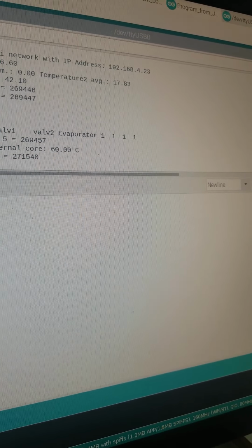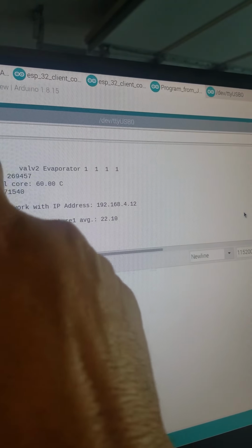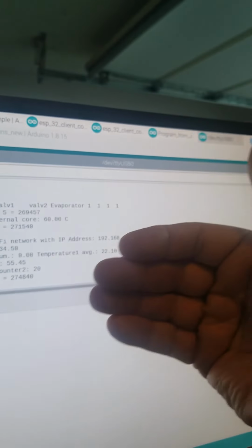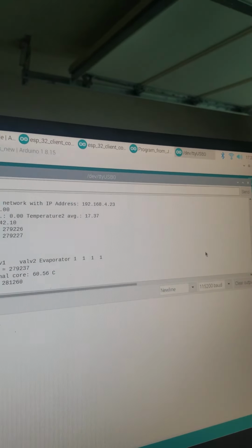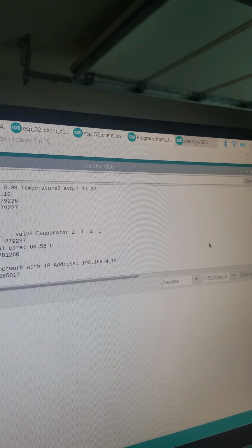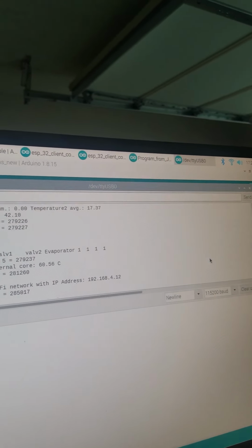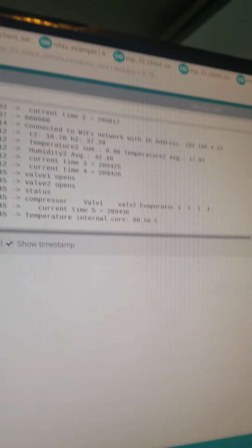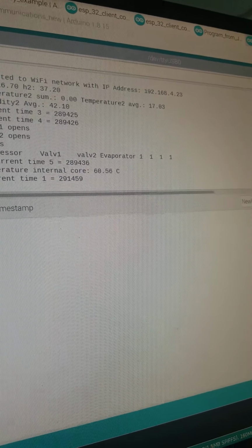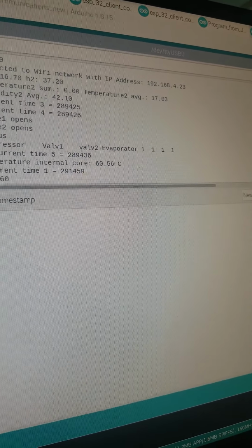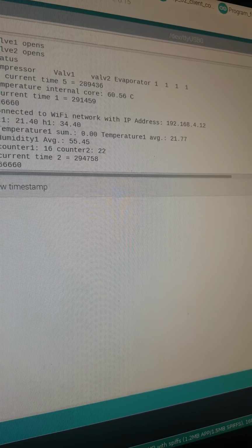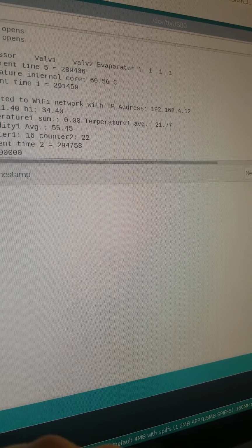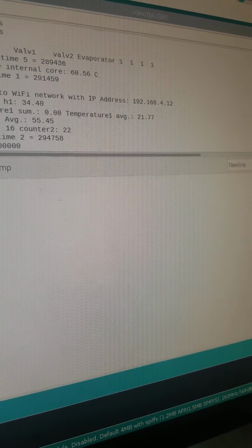You can see that, for instance, the temperature in the second mini container was like 17 degrees. The reason is that it's at the end of the line, so usually it's going to get more cold air, so it's going to cool down faster. Something that we need to think about is this. Mini container 1, the one that I want to use for cold temperature, is better insulated than the other one. So you are going to see the temperature fluctuation is going to be much higher in mini container 2.